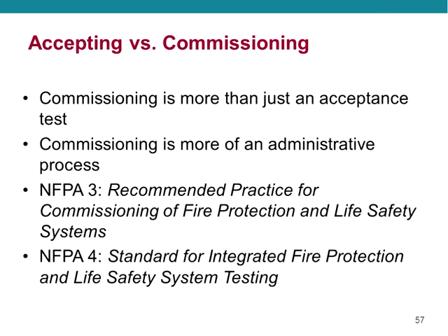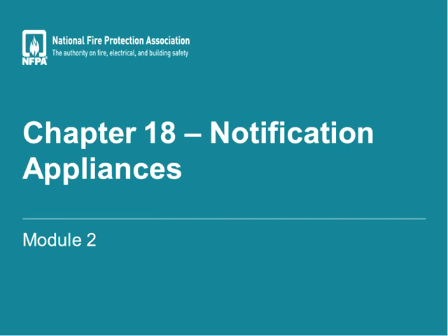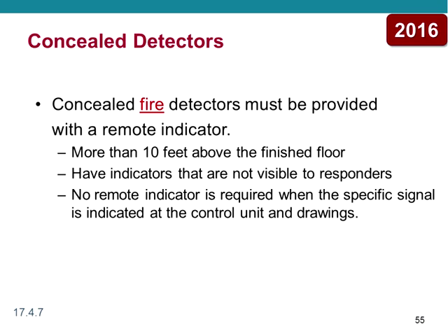Okay. Somewhere around in here, we had a question. Does it still apply to concealed smoke detectors? That was the slide. The answer is yes. A smoke detector is a fire detector. So the answer is yes. It applies to all automatic fire detectors to include smoke, heat, remote, or any kind of flame or optical detector, anything like that.